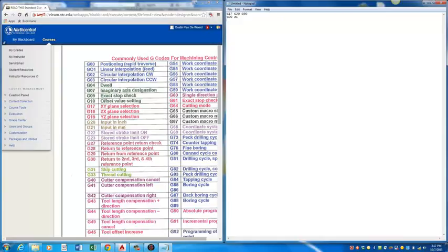The next move I'm going to program is G00, and you don't have to capitalize it, X0 Y0. This ensures that no matter who left this machine last, when I open up my program, the first thing it does is lift the pen up and go to my origin. So those are a couple commands that you just have to put in there to start your program correctly.